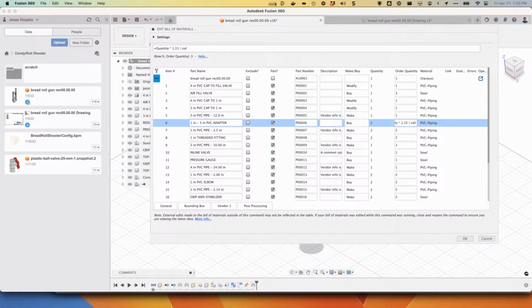Yeah. Generally speaking, the rule of thumb is, it's probably a formula, and as long as you have the elements of the formula captured as either design parameters or as other properties, you can write the formula. A great example of that is quantity times longest dimension gives you the total length of whatever material you might need, of bar or plank or whatever type of material. And then typically you would multiply that by some number for potential waste or overrun.